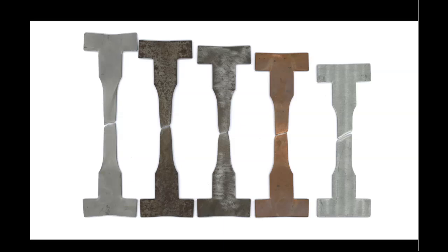So what we looked at in the first question, we look at the fracture strength in UTS. So the fracture strength, if it's close to UTS, it's brittle. If it's further removed from UTS, it's more ductile. So that's a giveaway. The same thing is about percentage elongation and percentage reduction in cross-sectional area.